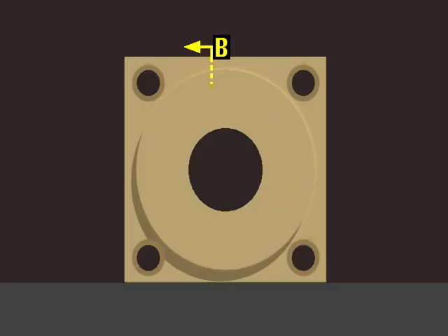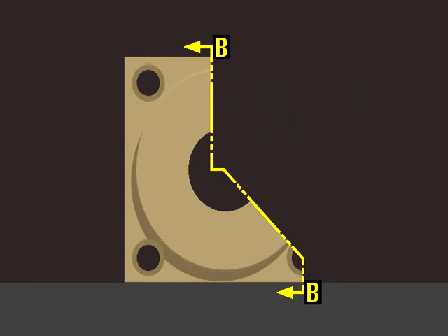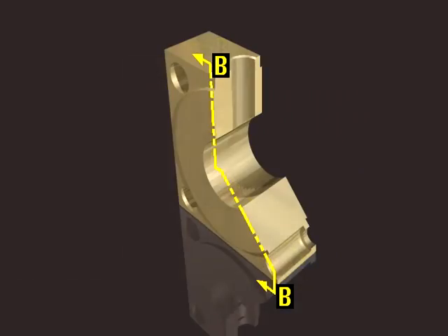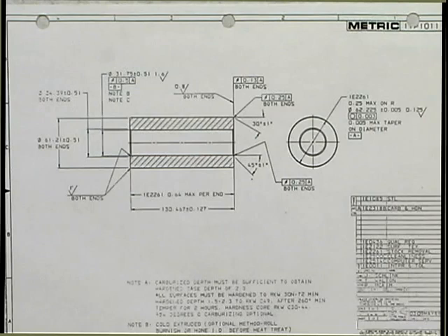If the part was cut through along cutting plane line B and the piece that the arrows point to is turned in order to see the cutaway area, we will see the features represented by section view B on the print. If you encounter a print with a section view but no cutting plane line, look closely at the print. If it is obvious how a section view relates to a normal view, the cutting plane line is omitted to conserve space on the print.